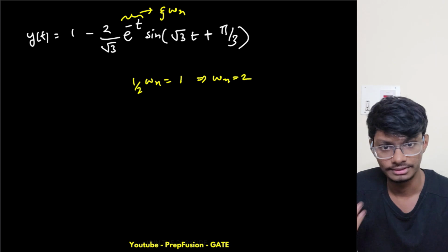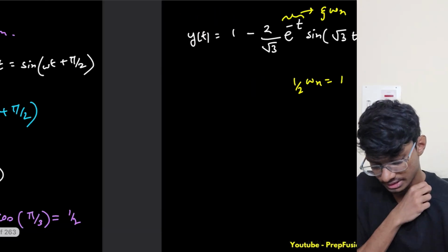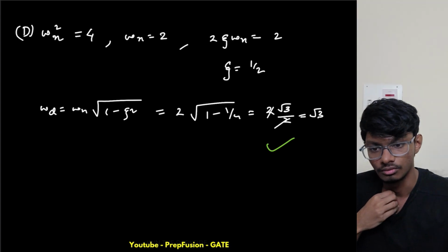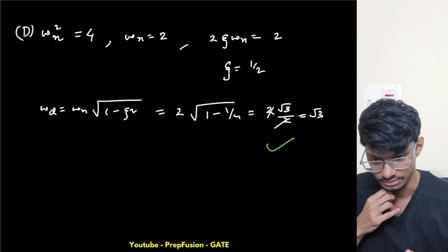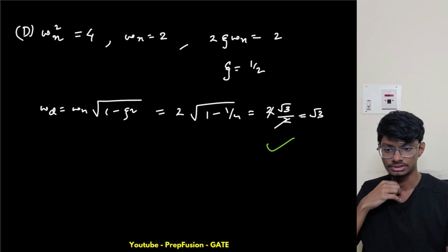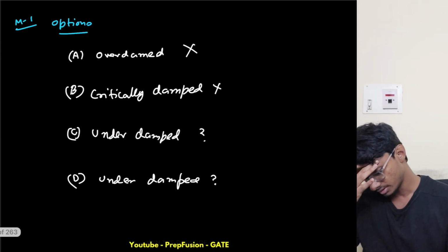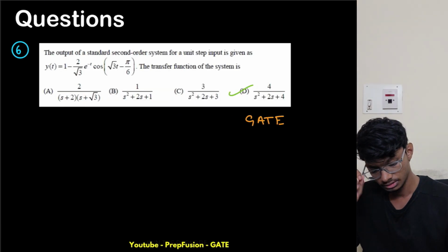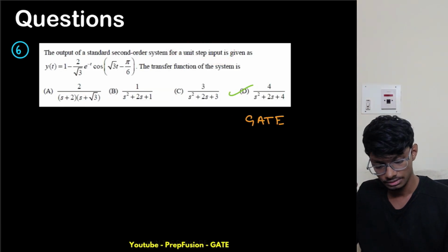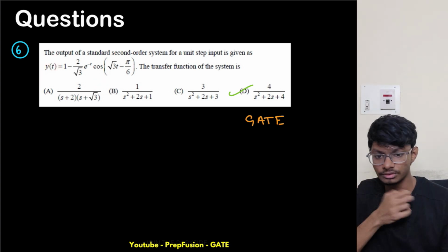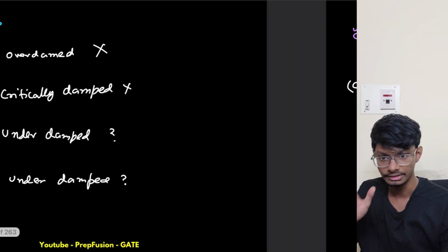So now I can write the equation from here itself. DC gain, how can I know DC gain? It is difficult to understand. For DC gain, you give a unit step input, find y of infinity, and from there you will get the relationship for the DC gain. Let me write, then you will understand.